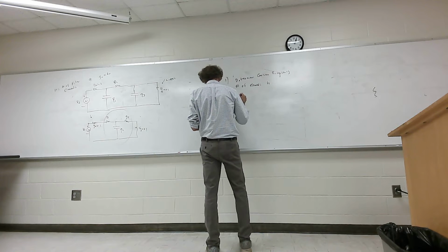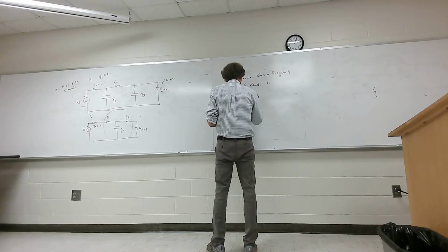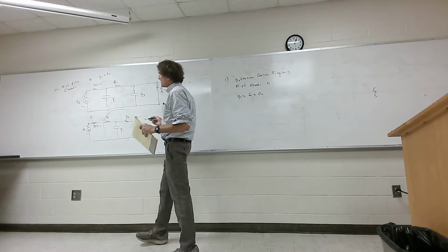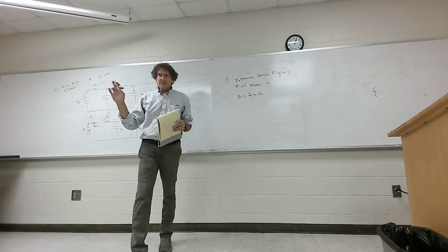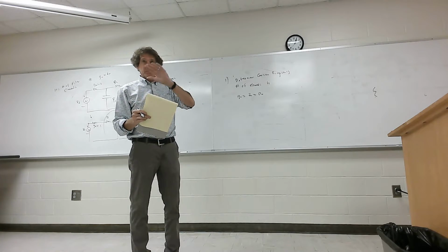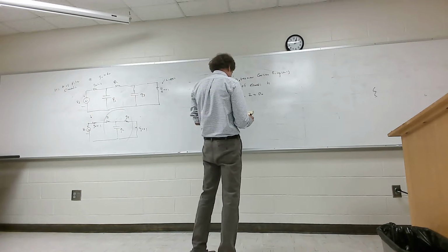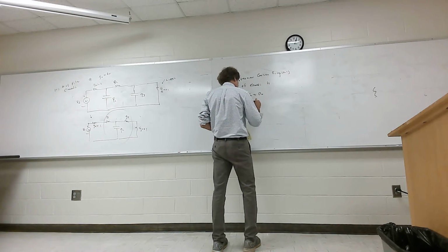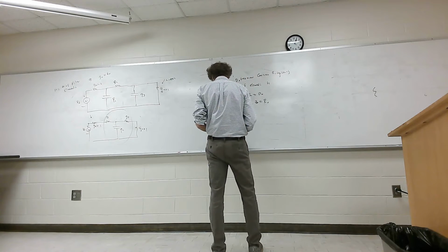So then, G naught is going to be equal to Z naught or R naught, and those are just the impedances. By the way, this is from microwave engineering, so typically this load is 50 ohms and this source is 50 ohms. That's just typical. These are what these filters are geared to. They can be geared to a lot of other things, but right here, his discussion in the book is about that. Then, obviously, since I just said that, Gn plus 1 is equal to Z naught as well, or R naught, so it's a characteristic of the impedance.